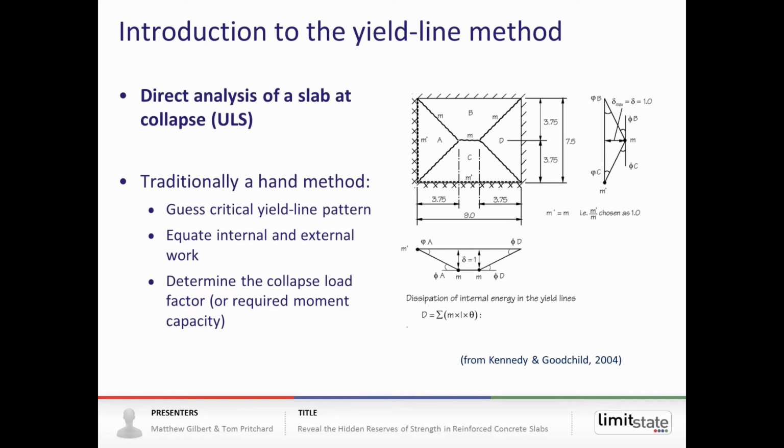So traditionally it was a hand method, so the user would guess a yield line pattern and then they would use the work method typically to calculate the load capacity. So you would equate internal and external work,